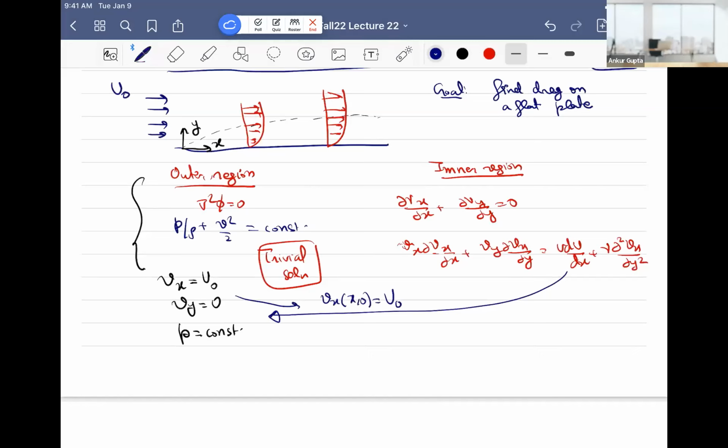So this, it's just a constant. So it's u naught du naught by dx, but u naught is constant. So that means that I can drop this term off. Okay, so you can think of it in terms of how Sauradeep mentioned that pressure is constant, and that term is really pressure gradient. So if pressure is constant, pressure gradient is 0. Or mathematically, you can see that velocity is u naught, and it's du by dx. Does it make sense? Okay, all right.